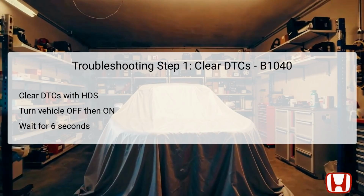This reset helps refresh the vehicle's systems and may clear transient issues. After waiting for at least 6 seconds, use the HDS to check for any DTCs once again. If DTC B1040 reappears, it's indicated that the problem persists, warranting further investigation into the wiper communication system.